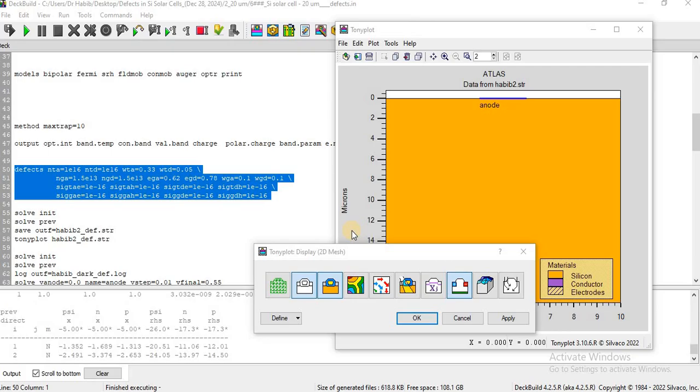In this video, I will demonstrate how to perform the simulation of semiconductor material defects. Specifically, I will focus on how various types of donor and acceptor-like defects influence the electrical properties of a material. We will explore key parameters like tail distributions and Gaussian distributions of defects, and examine how the density and energy level of these defects affect the overall carrier generation and conduction properties.